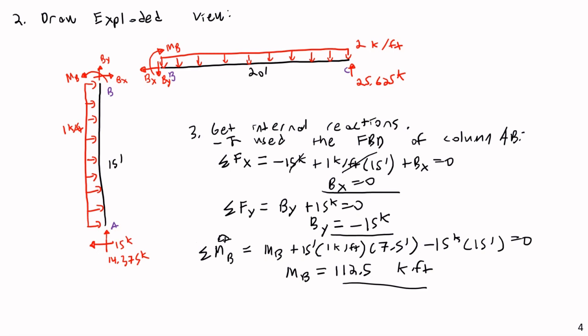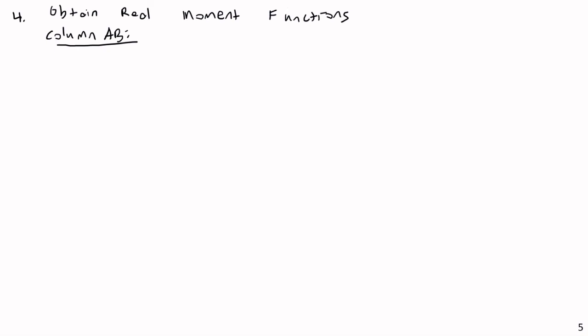It is imperative that you use compatible or identical sign conventions. So your 0 points have to be the same, or in other words, your origins have to be the same, and the direction of your positive has to be the same. If you don't do that, you'll screw this up. And maybe you'll kill somebody, so who knows.